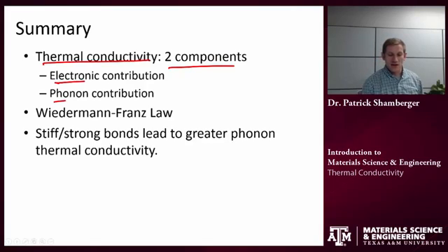There's the electronic and the phonon contribution. If we think about the electronic contribution, we can get to what's called the Wiedemann-Franz relationship. And so this is just observing that as the electrical conductivity increases, the thermal conductivity also tends to increase. Finally, if we think about that phonon contribution, the stiff, strong bonds tend to have higher phonon-based thermal conductivities.